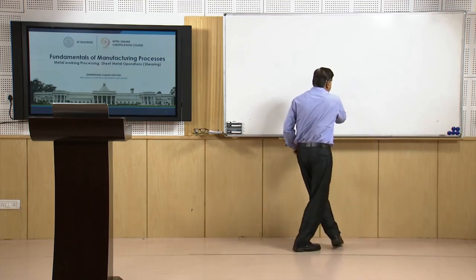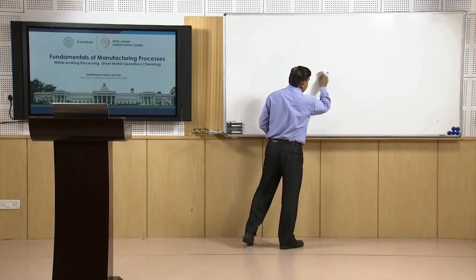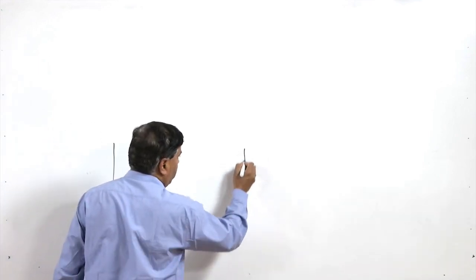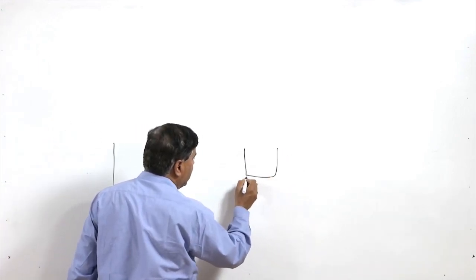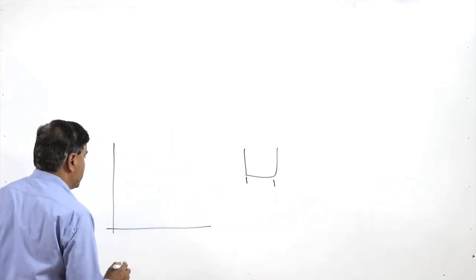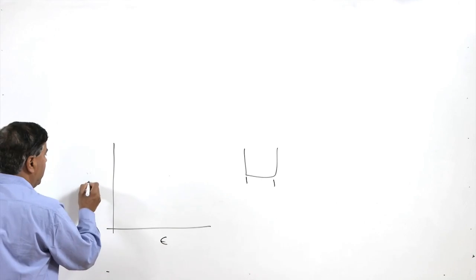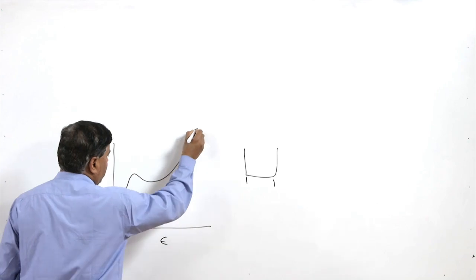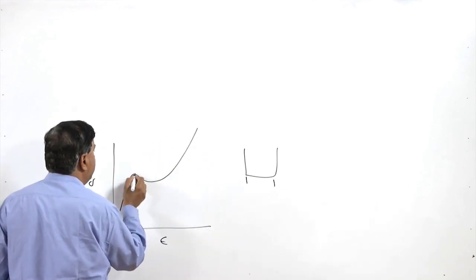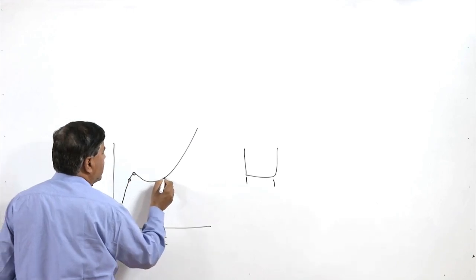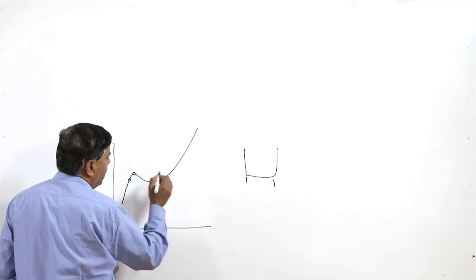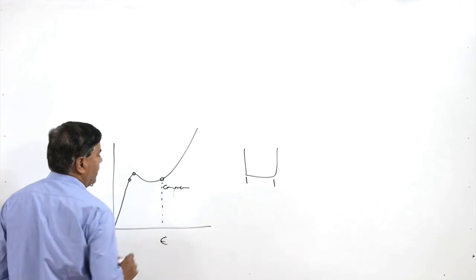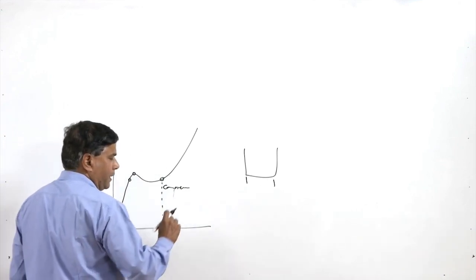sheet metal. So, depending upon the distance traveled by the punch inside the sheet, we get different strains. As the punch moves down, it will lead to increasing compressive strain in the sheet. So, the x axis is showing the strain and the stress is on the y axis, then the diagram that we get becomes like this. Here this is the yield point, this is the elastic region, and this is the plastic region where some compressive strain has been induced, of this much magnitude, due to the entry of the punch